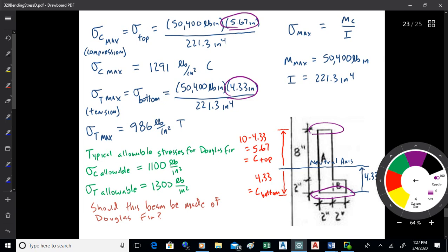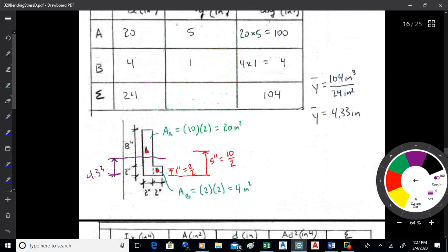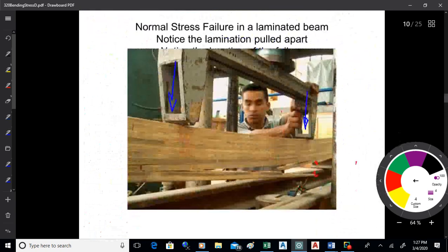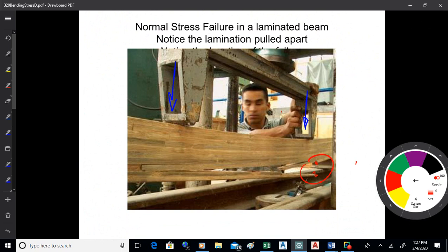So that's why we're analyzing that, by plugging in these values of C. Now you might say to yourself, why do I care if just the edge of the beam is failing, for that one C value? The reason is that failure propagates. Once things start to go, you're in trouble. The whole beam will fail. The initial failure happened right there, but after that popped, the whole beam cross-section is different because you don't have the full cross-section for strength. Then the bottom couldn't hold it, and it just works its way up. So that's why we just analyze the edge. That's the worst place, and that's where problems can start to happen.